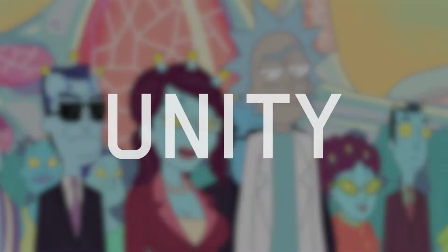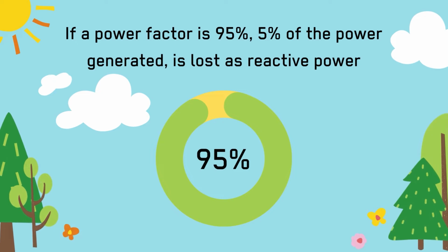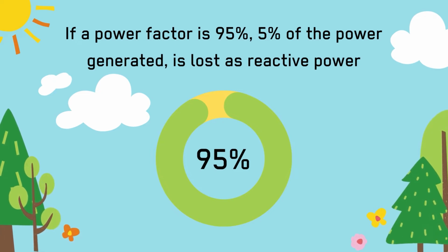Our ideal power factor would be 1, also called unity, which means 100% active power. When something is 100% active power, it means that all the power that's being generated is also being used for electrical loads and no power is being wasted. If a power factor is 95%, for example, this means that 5% of the electricity being transmitted is lost as reactive power before it makes it to the electrical load.